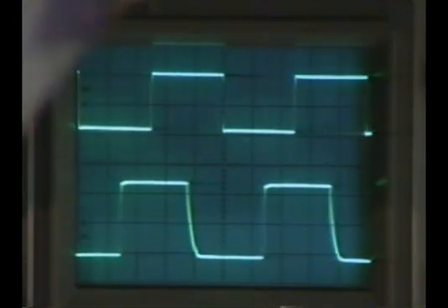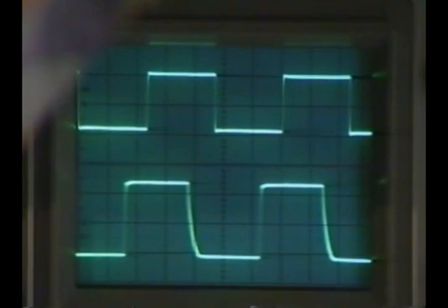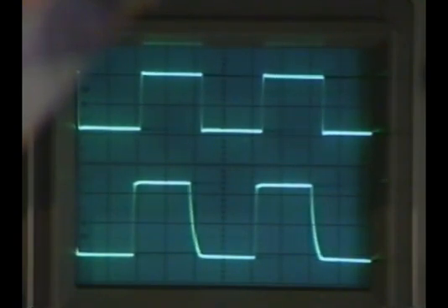Okay, so in other words, that's free running. It's about 90, and I keep this up. That's okay. There you go. So it just lost track. And in fact, what's interesting? There you go. So I got it back again. Okay, so it's not bad, actually. It goes almost up to maybe 10 or 15 degrees, and then it loses it completely. What's happening now is the poor thing is out of its range. If you remember, that phase detector has kind of a sawtooth picture. And so this is a very, very complicated nonlinear system now, and it's jumping all around.